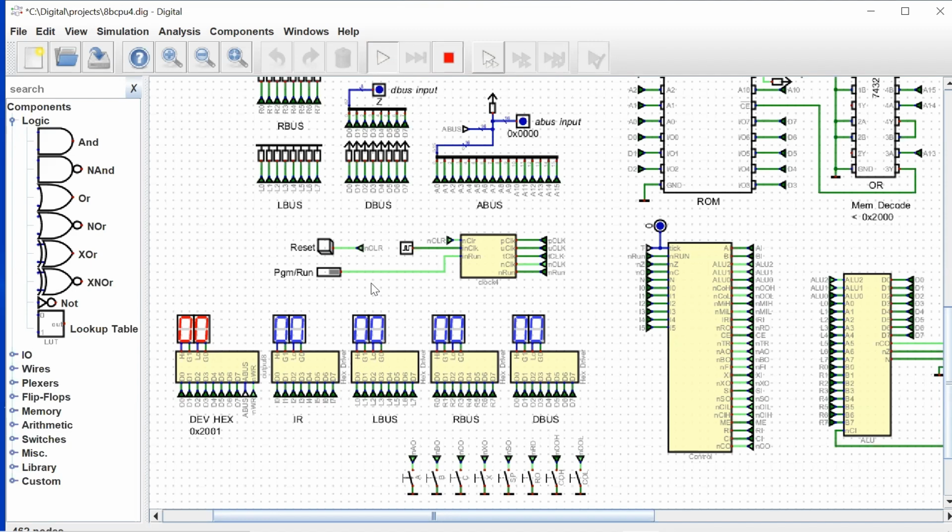When we get to our hardware implementation, we will have a reset button, but we'll also have a simple RC circuit that will keep this low for a short time. That will bring up the clock and the computer in a starting state, and the computer will just run itself without having to hit the reset. Okay, we're good to go here.